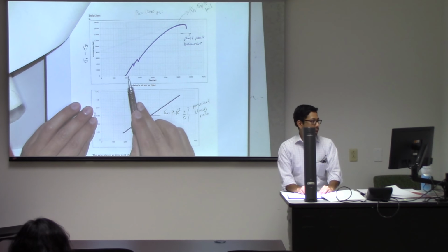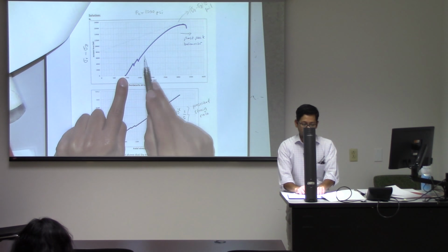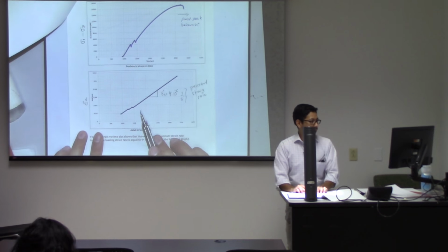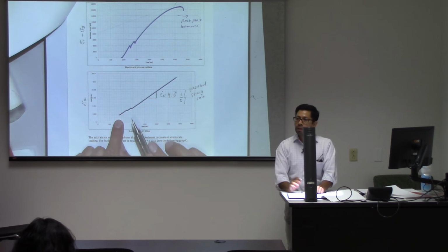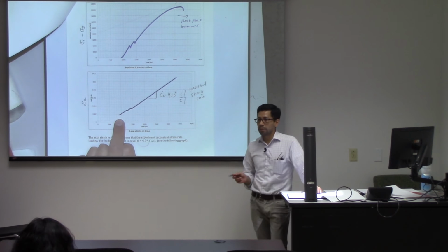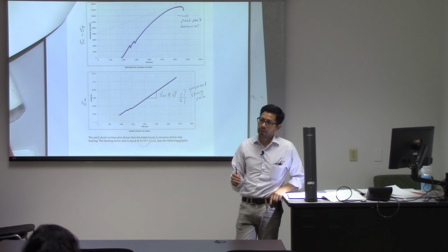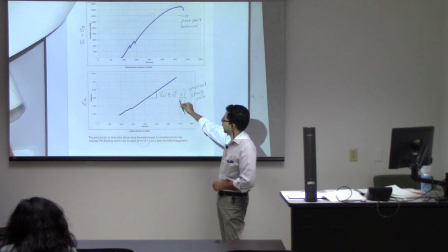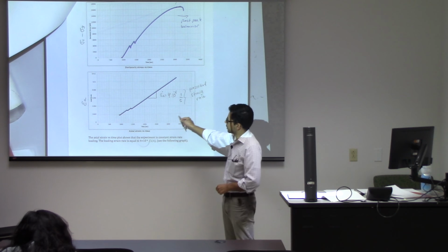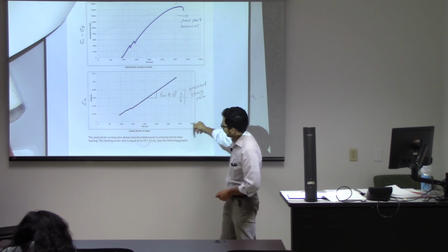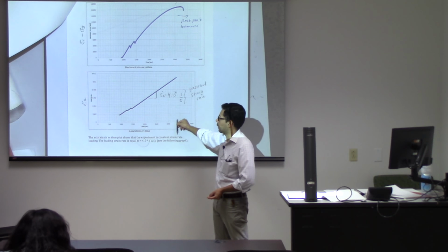So at the very beginning, there is no deviatoric stress. You apply deviatoric stress, the rock starts to deform, and this is the imposed axial strain. Many of these tests, the way that we run them, and this is the same that you're going to do in the lab, is you fix a strain rate. In this example it was a strain rate of 4 times 10 to the minus 6 per second, which for this test required about 1 hour to run. So this is how slow it was.